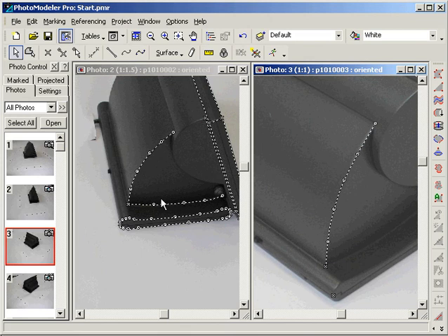We want to add a surface to this section, but all we have is the two curves. There are a couple of ways to do this. The boundary patch mode can create a surface using 3 or 4 curves. We only have marked 2 curves, but this third curve between these 2 points is implicit, so we are able to use a boundary patch. We can also use the loft.